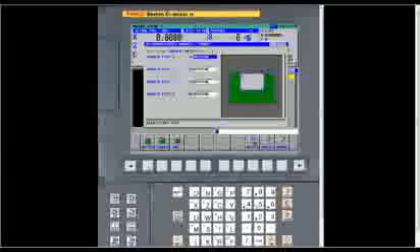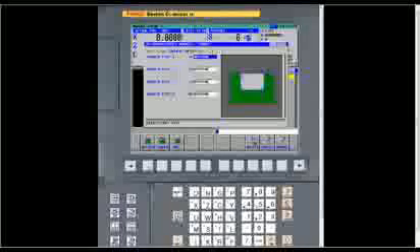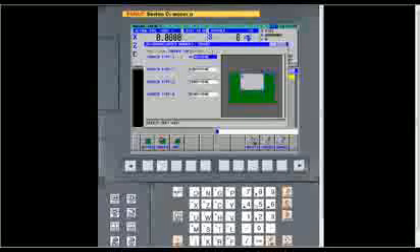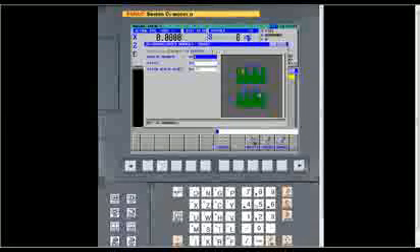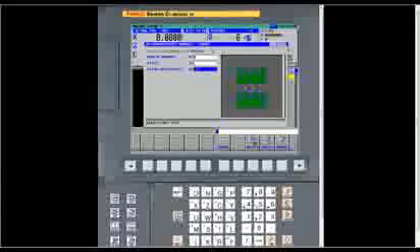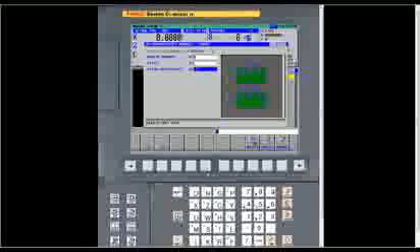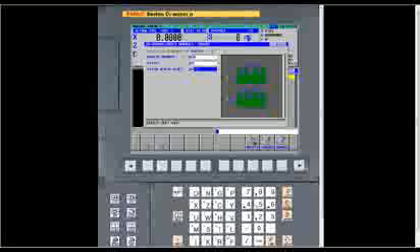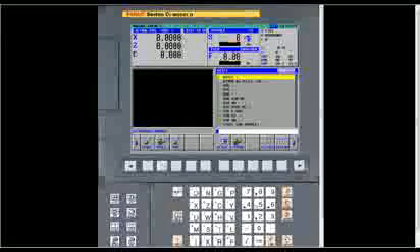Then another good thing about the grooving, you've got the capability of, on all 4 corners, bottoms also, where you can either define a chamfer or an arc, or nothing. You can make it be a sharp corner. And then obviously you can do multiple grooves. However many you want, the pitch, and then which direction they go, whether Z minus or Z plus, based on the geometry of your print. So that's the grooving cycles.